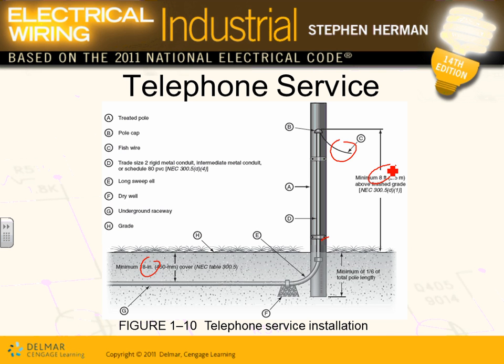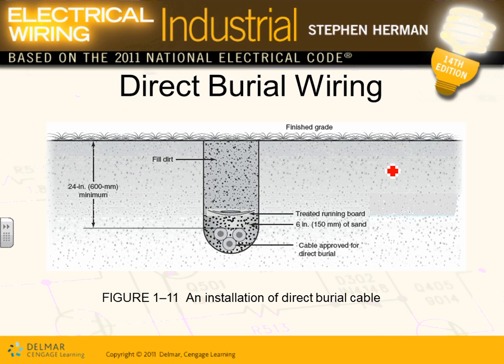If it's underground, typically it will be through a handhole or manhole. Now your underground cables, guys, direct buried cables. There are direct buried underground cables at 24 inches with dirt. Isn't that the detail that you guys did for me? That's exactly what you did in your details. Direct buried cables are approved for direct burial, and we buried them.